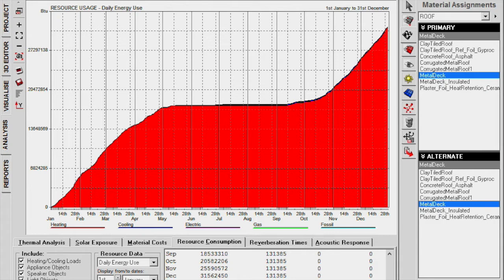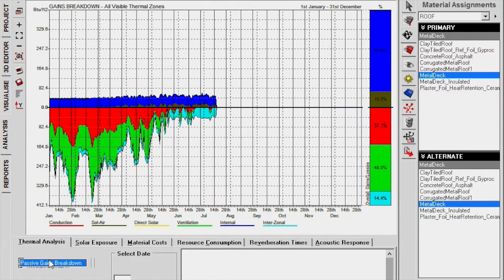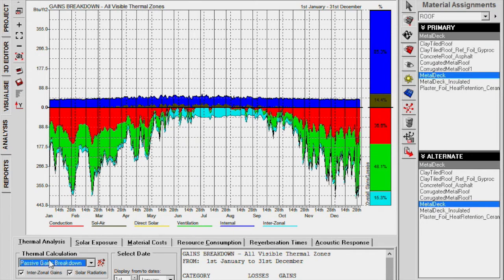So even if we now went back and looked at that thermal analysis, if we look at the conduction and the percentage of heat that's being lost, it's relatively small. At this point, we are losing more just through ventilation of the space than through the conduction. Okay, so changing the R values changes the conduction. That's really one way we can approach that. Let's talk about some of the other ones. Direct solar, we're going to get into that.